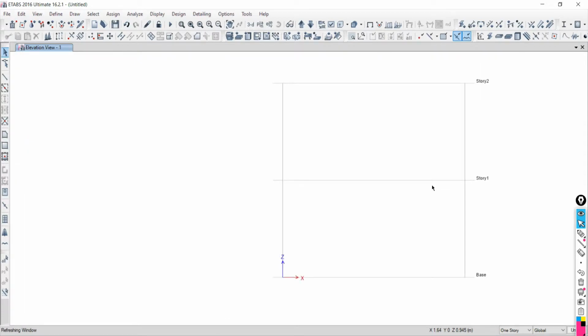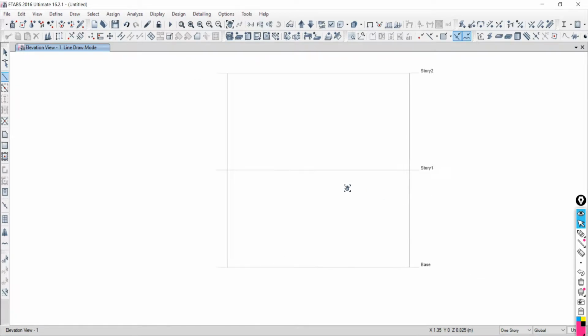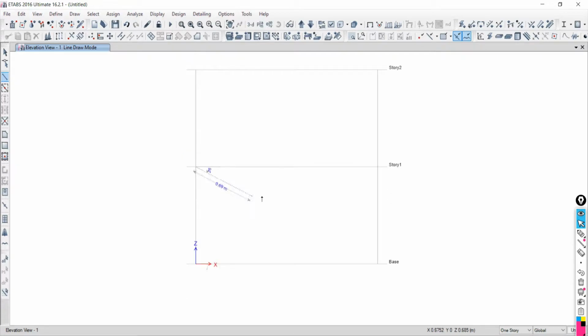Okay. So in one turn, I would like to model the beam from first end to another end. This is the first point. Take your cursor and don't click over that until you are getting the grid sign like this. Then click over that, freely move to the another point and then click over that, then right click. So you will have this kind of frame.